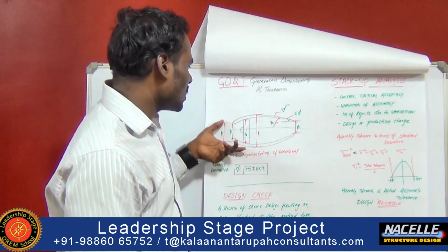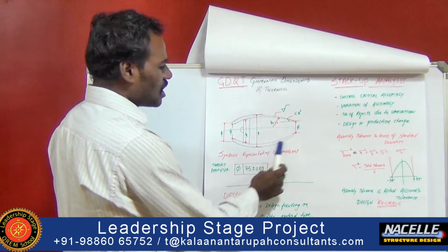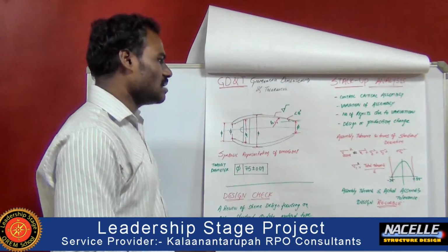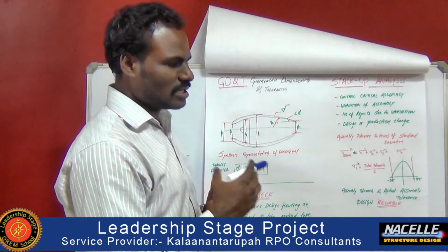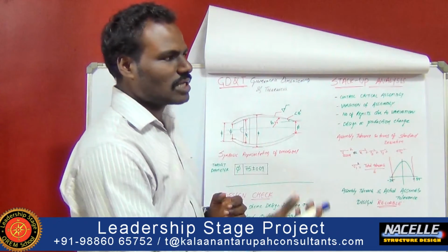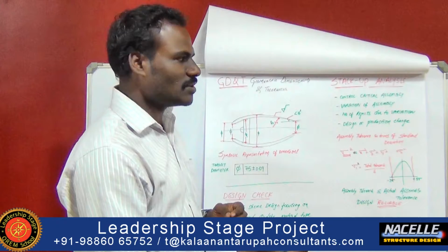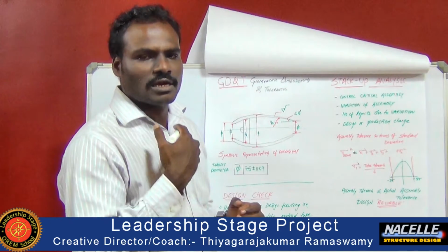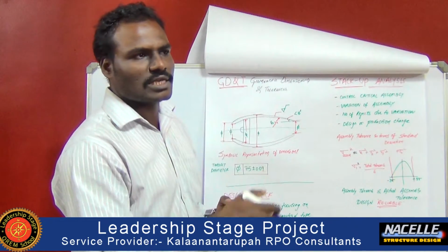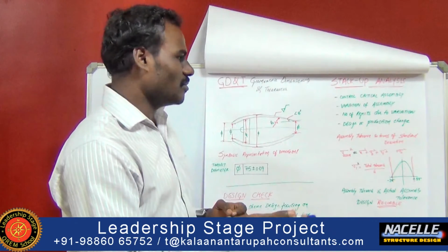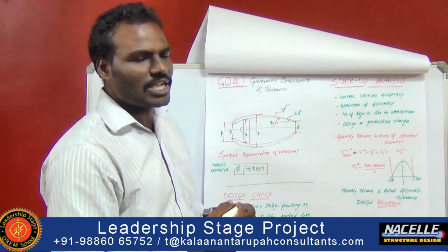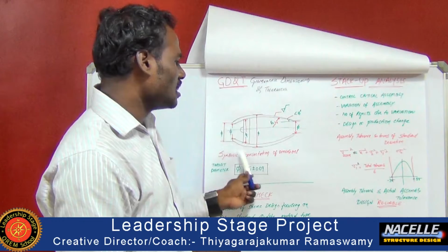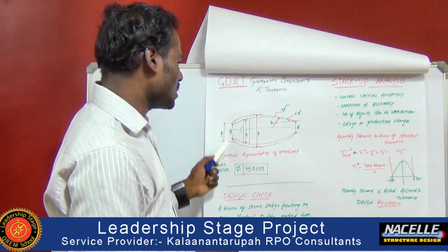using some symbols. Here the graphical representation of the nozzle has been created, showing the dimensions and the tolerances which can be represented using GD&T. GD&T helps us if we are developing a product, a part separately, as we can specify the dimensions applied and the tolerances over it. Whereas for a whole complex assembly, we cannot specify the dimensions at each and every part of the assembly, so we communicate the design with the symbols specified here. With respect to the nozzle dimension, the GD&T tolerance has been represented here.